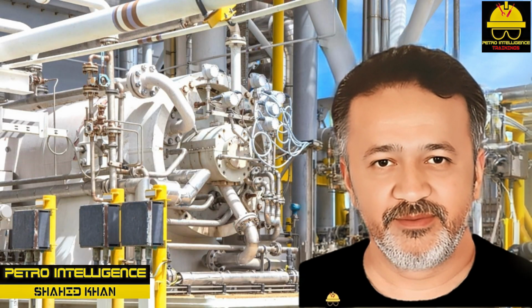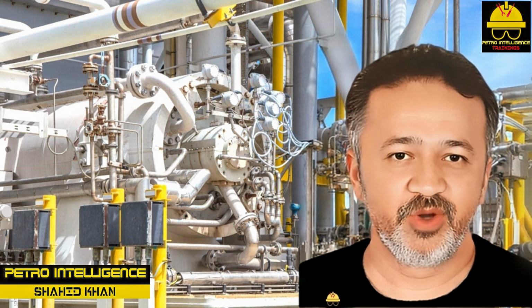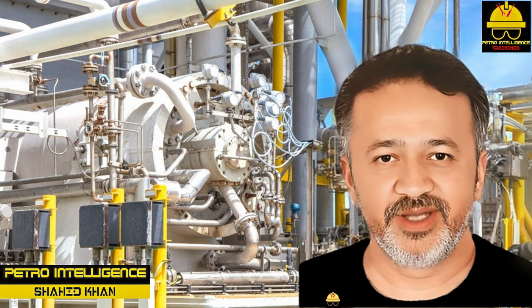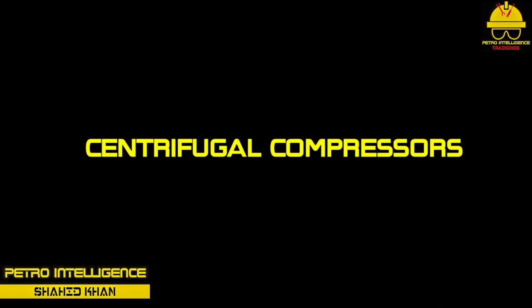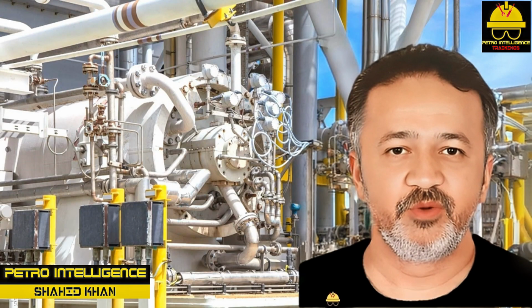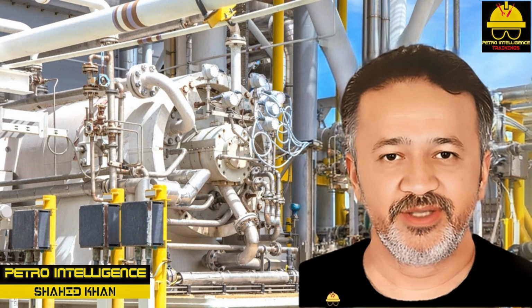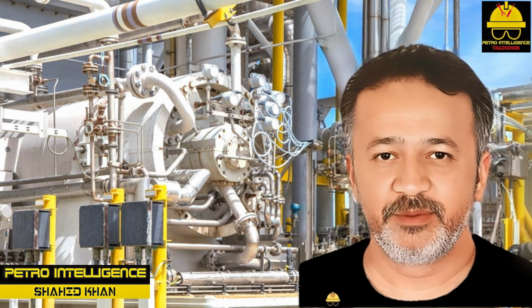Dynamic compressors. Dynamic compressors are classified as either centrifugal or axial flow. Both types operate by changing the velocity of gas and converting energy to pressure. Centrifugal compressors. During operation, gas enters a centrifugal compressor at the suction inlet and is accelerated radially by moving impellers